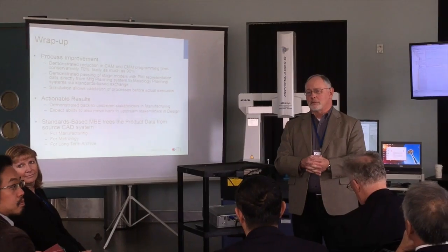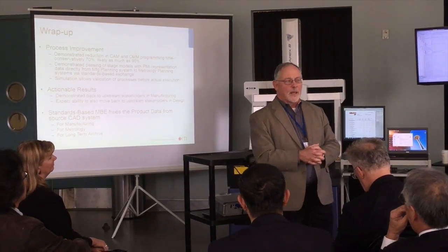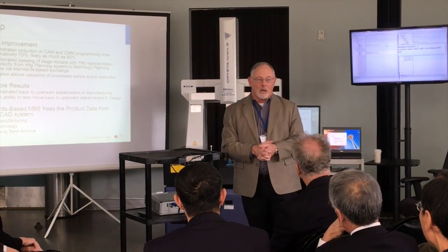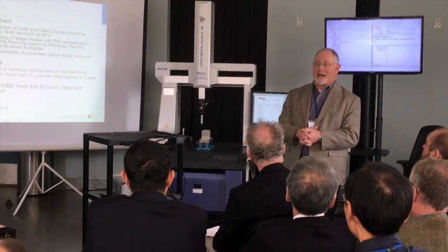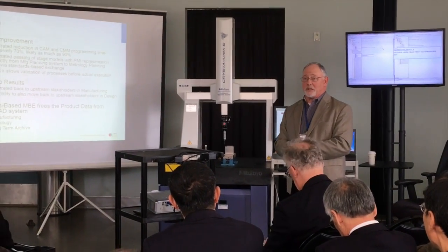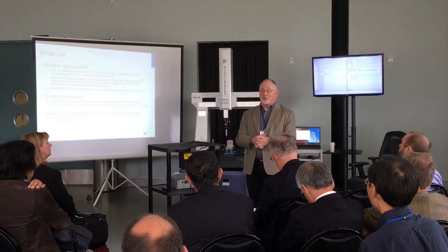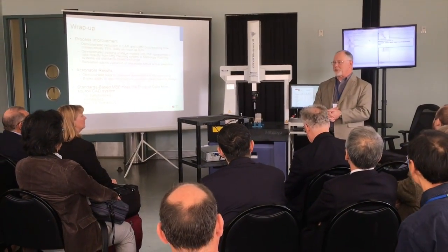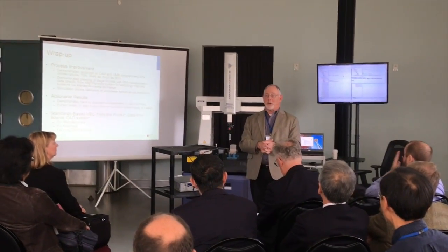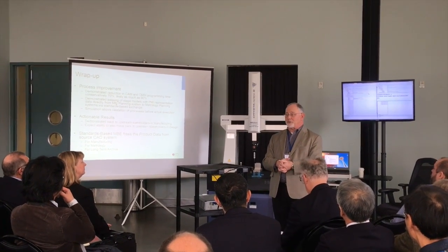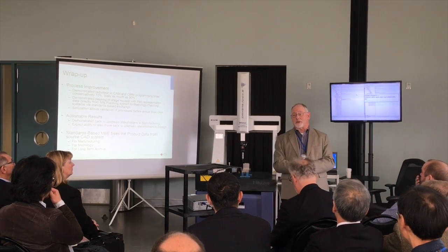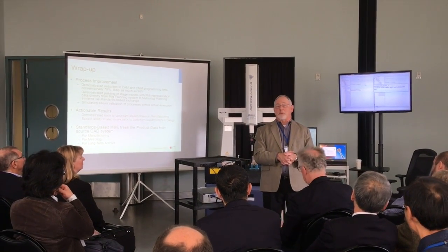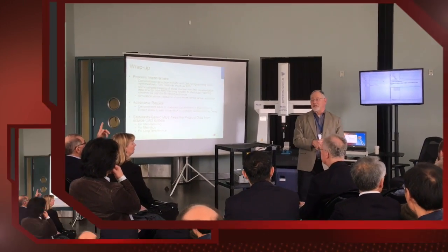And any test bed for qualifying the tools of the vendors and application of the partners? We have been doing work for the PDES ProSTEP CACs on validating STEP data and particularly PMI data content in 242 format for some time now. I think this is probably the third or fourth round that we've been doing validation for STEP. There are similar activities in the JT Open interoperability forum, and also the 3D PDF interoperability forum. So yes, there are mechanisms to validate the transformation of the data from format to format, so that you prevent lossiness in the exchange.